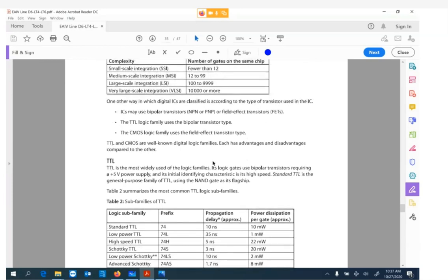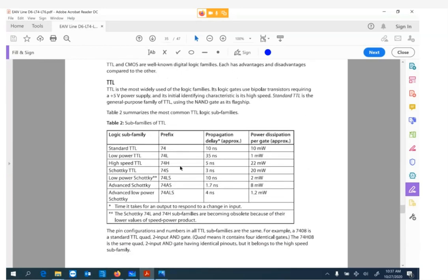Something called TTL logic. We had TTL cards at our mill for our scanners, and of course, different voltages and different speeds, and of course, different power consumptions. Now they are very susceptible to static, right? So static can really mess these things up. And you don't even have to touch it per se. You only have to get close to it, and over time it will degrade it.